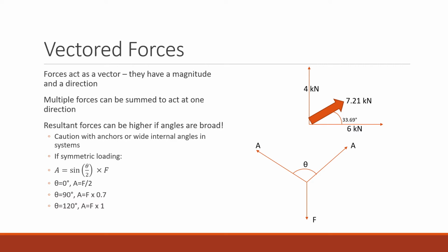The force is split between the two. Cool. Life is good. You can use less robust anchors to make that work. Nice. Now, as we take that further apart, it's important to know that the force that we experience on each one of those anchors increases by the sine of that internal angle divided by 2.